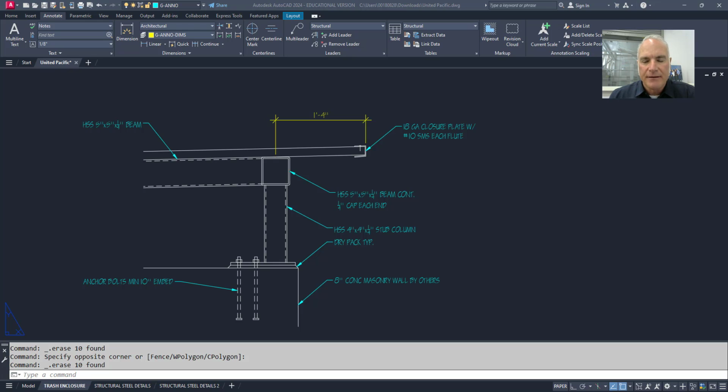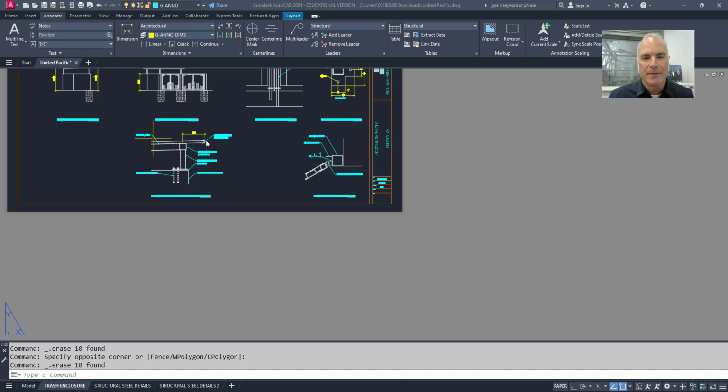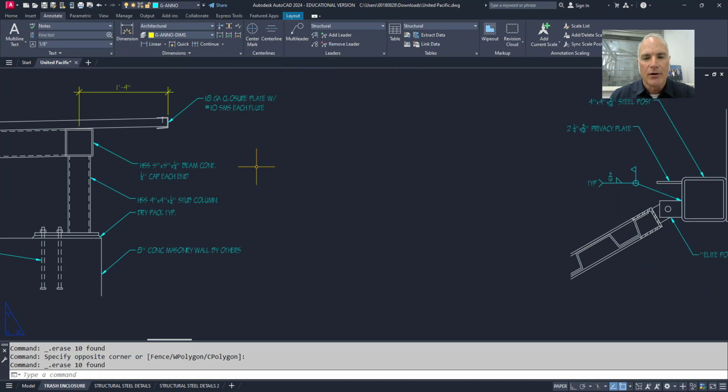You can see that in this drawing, I already have a multi-leader style set up, but I'm going to go through how I created this one, and how to create another one in addition to it. So the first thing you want to do is make sure I'm working in paper space here. Usually your multi-leaders go in paper space.